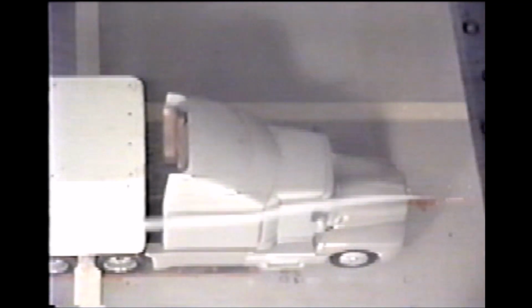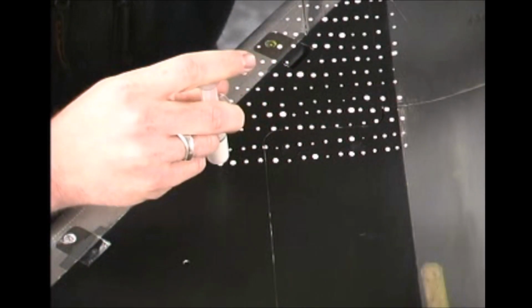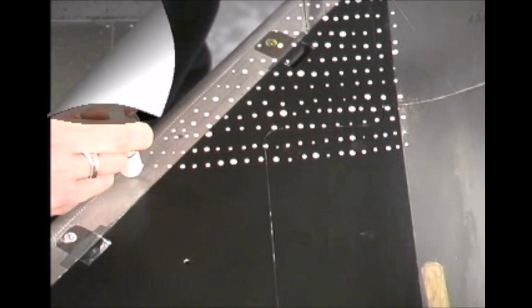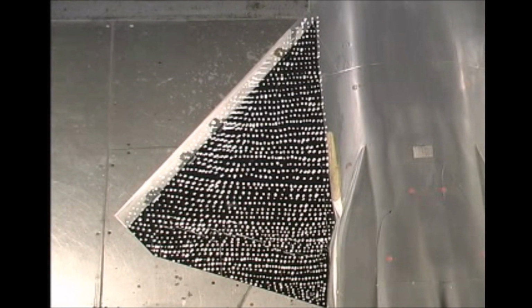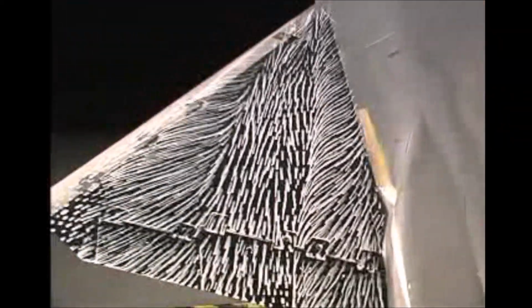Here we introduce smoke into the airstream and see how it behaves around the model. This is really useful for helping estimate things like boundary layer thickness or observing other off-body flow field characteristics. Conversely, if you want to understand how the flow on the body is behaving, you can use techniques such as polybutene oil spots. These are dots of viscous oil that you place on the model when the wind is off. When you bring the wind up, the oil runs in the direction of the streamlines and helps you visualize the flow field on the aircraft.